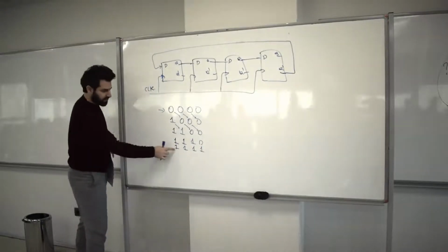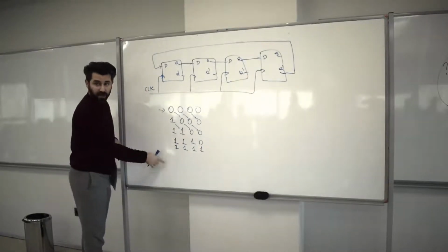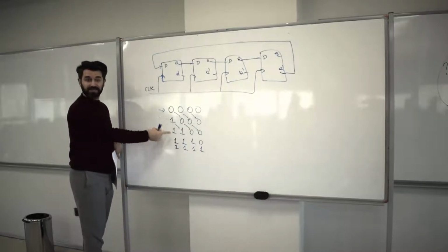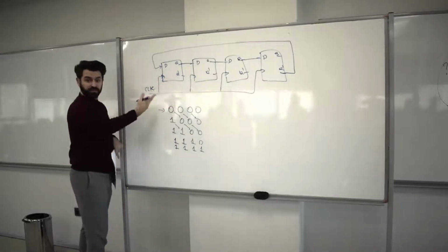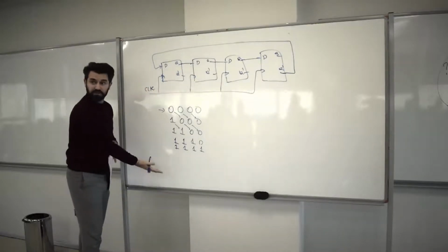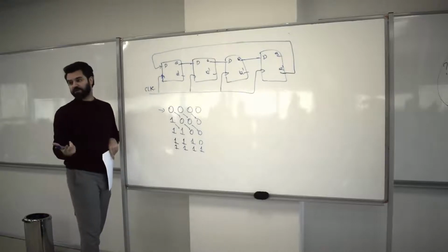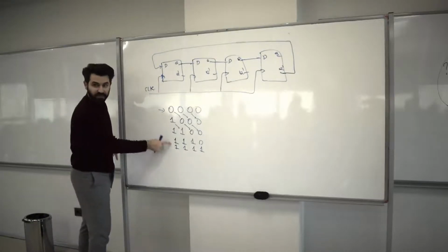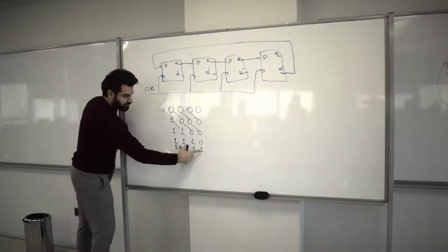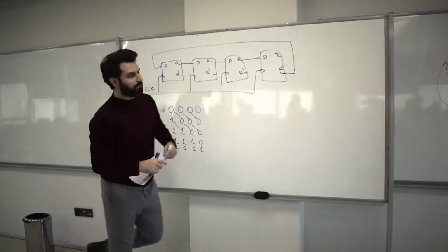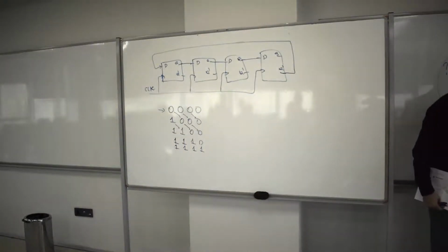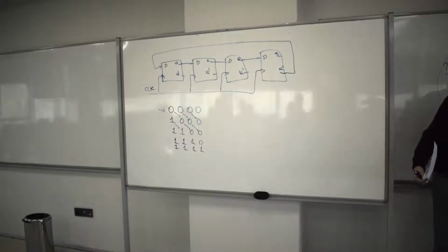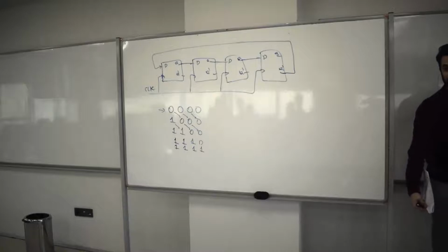We're not there yet because you have to keep doing this until you hit 0, 0, 0, 0 again. That is going to create your period, because these are sequence generators, by the way. They generate sequences, and you have to figure out the period of the sequence generator. The period is not there yet because we're still generating absolutely different sequences. For example, for the ring counter, I started at 1, 0, 0, 0, and then went to this one, and then this one, and then this, and then I stopped. Why? Because the next sequence is going to be identical to the first one. That's why.